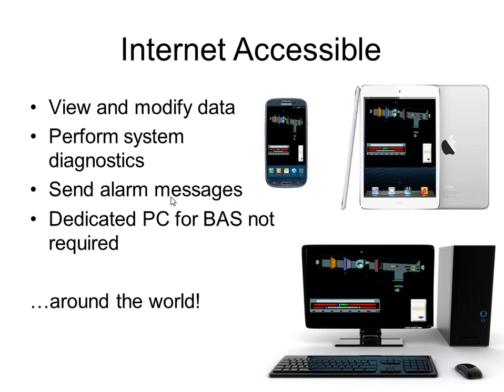You can broadcast these on the internet, get them on your smartphone, on your iPad or tablet, or any other computer connected to the internet. So this is a great feature to have with a DDC system so that you can remotely look at what's going on, see what the temperatures are, and diagnose what's happening. You can get alarms. Very nice feature, something you should always try to include with a VVT or any DDC control system.